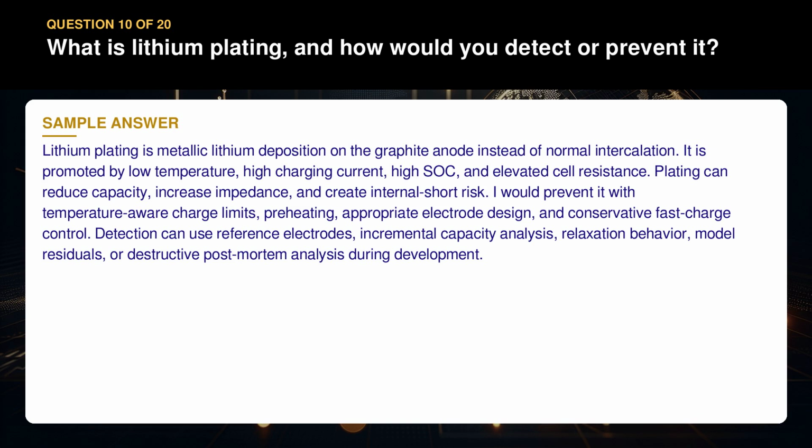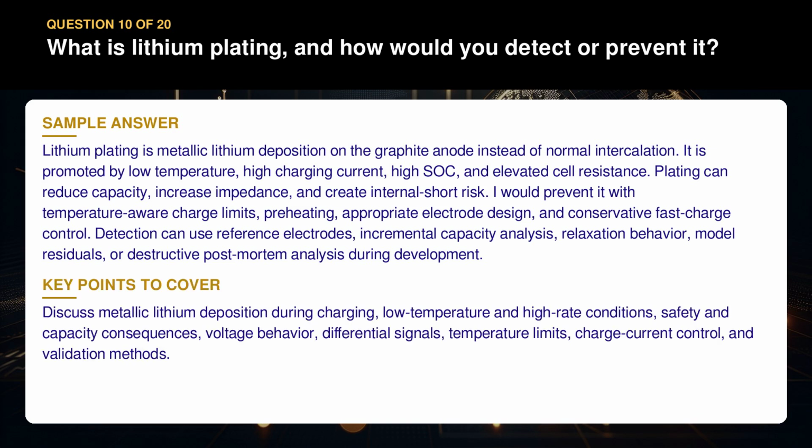Detection can use reference electrodes, incremental capacity analysis, relaxation behavior, model residuals, or destructive postmortem analysis during development. Discuss metallic lithium deposition during charging, low temperature and high rate conditions, safety and capacity consequences, voltage behavior, differential signals, temperature limits, charge current control, and validation methods.